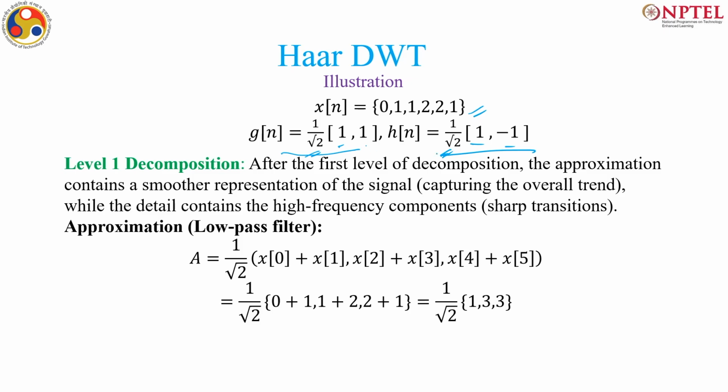Now, if we convolve this, we will typically get the same length, and then, as I said, we will be downsampling by a factor of 2. That means we will pick up alternate samples, and hence the length will be half, because after convolving the length will be kind of the same, then we will downsample to make it half the length. So, here you can clearly see that.